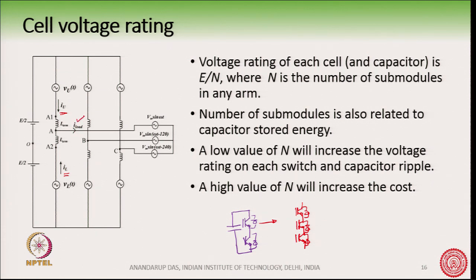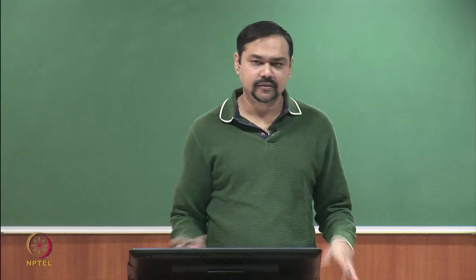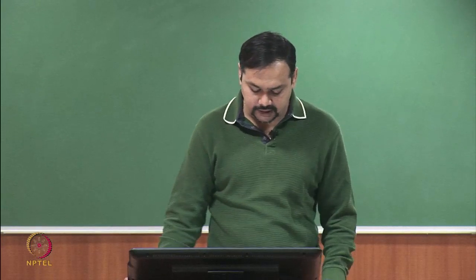Now, the voltage produced by this converter is almost like a sine wave. So, the load current for this converter, we can assume, is almost like a perfect sine wave, and can be represented by the equation I load equal to I max into sine omega t minus phi, or something like a sinusoidal function we can write.